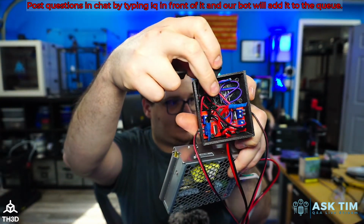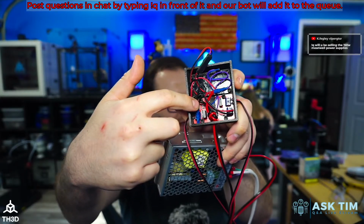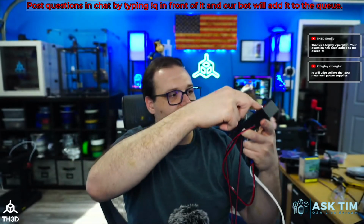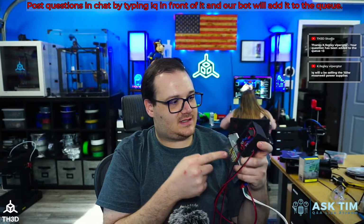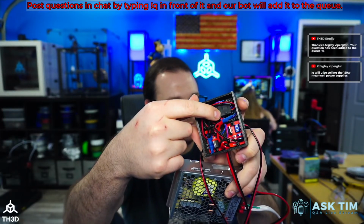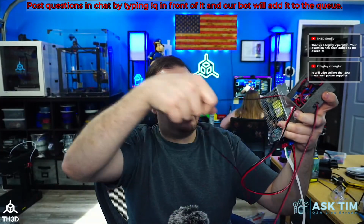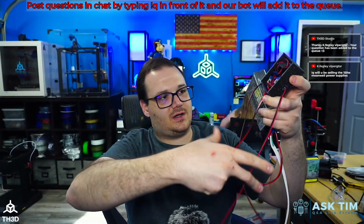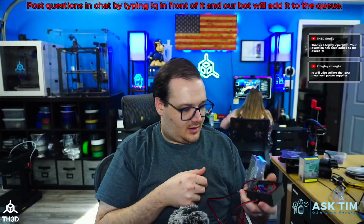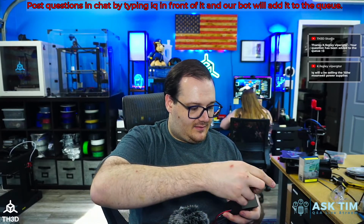But you can see the ESP8266 in here, and these are two of the little MOSFET boards that we actually sell already. These are good for up to 5 amps. This is to control 2 LED light strips, and 12 volts comes in here. This little thing is a step down to give the NodeMCU board 5 volts, and then I have 2 outputs here, one here and one here. These are 18 gauge wires, and the one going in here is 14 gauge. This is a 100 watt power supply, so it's only 8.5 amps, but I need about 7 amps for the lights.